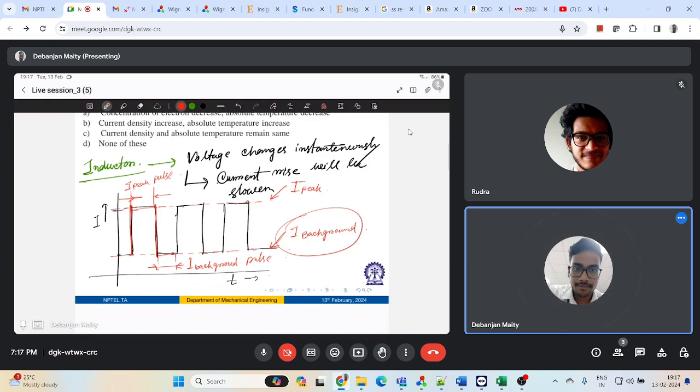Because my temperature is increasing beyond a certain limit, I need to reduce or increase my voltage and current in such a way that it will control the arc length. So there will be a feedback system in this transistor power supply unit. Now, the transistor can be made to behave something like a variable resistance, right?